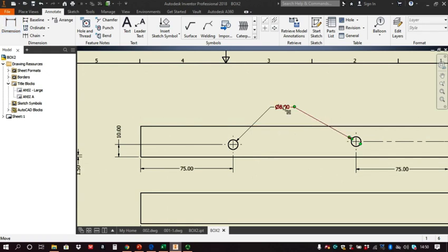So, what you should be using, and I do apologise because my laptop will take forever to do this, is the hole and thread tool. In this particular case, when it comes up, it will actually specify how deep the hole is. Now, if I know the depth of material, I can tell if that goes through or not. And that was why it was important when we drew the actual drawing that we extruded to the correct depth and not any depth. Okay, there is a big distinction.